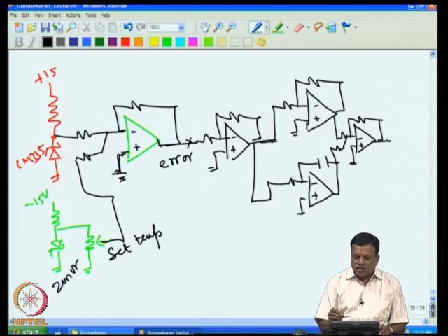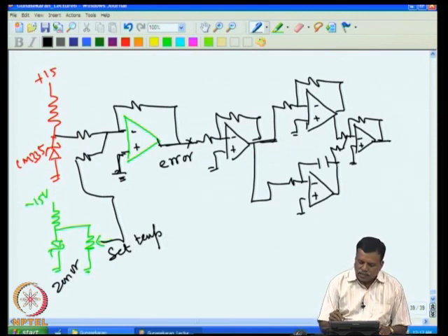So essentially you are adding the integral output and the proportional gain. This gives you the gain. So this is the error voltage. When temperature goes up, this increases, then correspondingly this is amplified and it will go minus, and that will be inverted and you will get a plus. And then whenever error is there, this slowly charges up the capacitor, and this voltage also will go towards minus, and that will become plus.